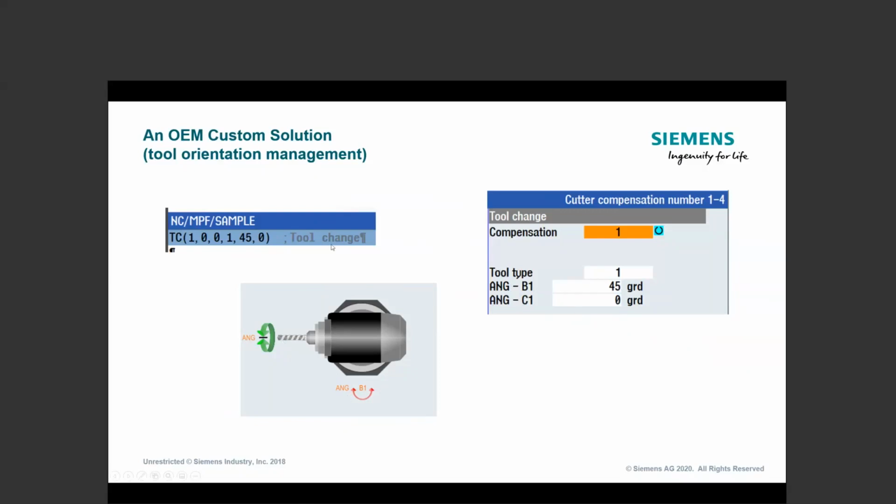Even though you did a TC command, if you don't physically drive with a rapid B and a rapid C, or whatever the spindle designation is, it's going to run totally wrong positions. For us, doing it through Cycle 800, it not only makes the calculation for you but also moves the axes, so it really combines two functions in one. But these are pretty high-technology machines, so I would defer to the OEM.